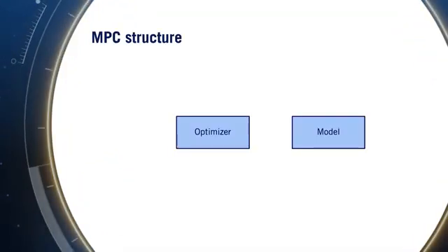We can visualize the receding horizon or MPC algorithm using the following block diagram for a controller. We have two main blocks, an optimizer block, which is the core MPC component or receding horizon control component, and the dynamic model. The model takes in the past inputs and state from time t-1, and it takes in the output of the optimizer, which is the current sequence of inputs u at each time step in the horizon.